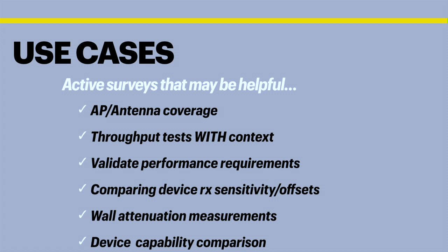It's all about context. Wall attenuation, that's one that I think we're all familiar with, and I don't know if those guys are here from that new company, but that is creating that tool, but measuring the walls to get accurate data for your surveys, for your designs, right? So that our walls can be accurate, so that the design can be as accurate as it can be. So wall attenuation measurements would be another one that would be very important.